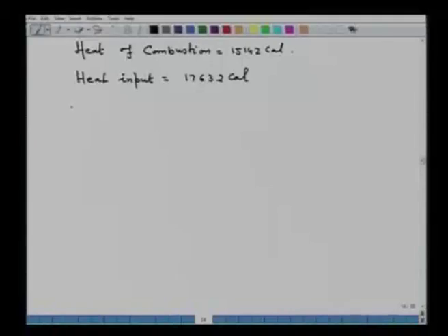I put the Cp values. So, if I use Cp is equal to A plus 2Bt, then the Tf is equal to 1472 degrees Celsius. Now, mind you, here I have used Cp is equal to A plus 2Bt.